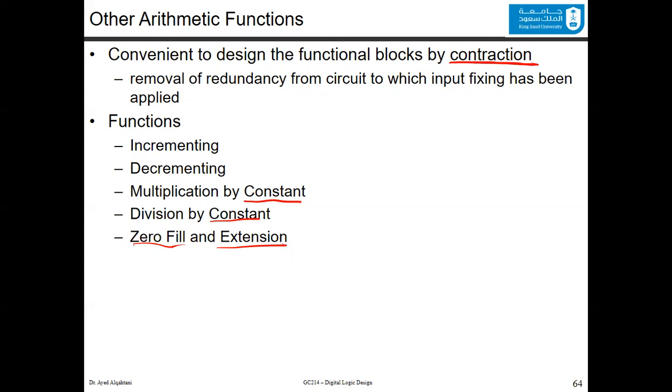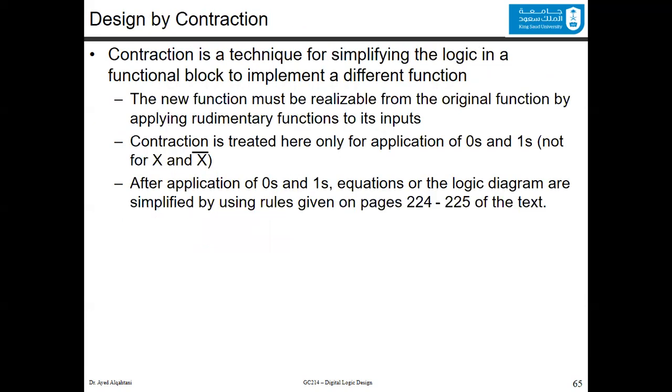To show you the idea of contraction, the design by contraction is the technique to simplify the logic gates in a certain functional block to implement a simpler different function. The new function must be realized from the original function by applying rudimentary functions to its input. Either you fix the value, or you pass it, or you invert it. The contraction is treated here only for application of 0 and 1, not X and X bar.